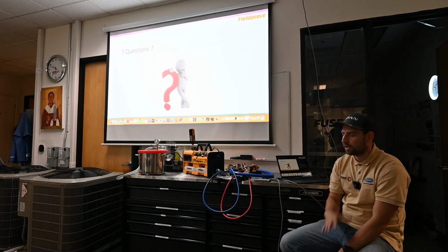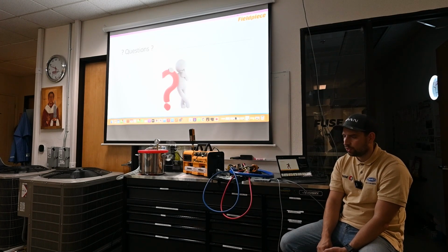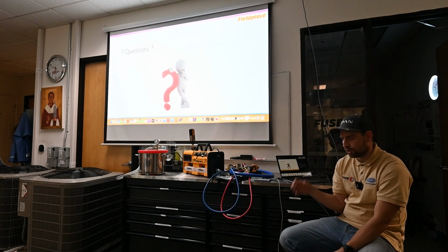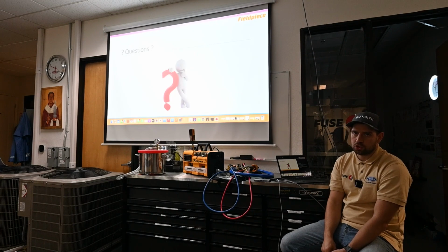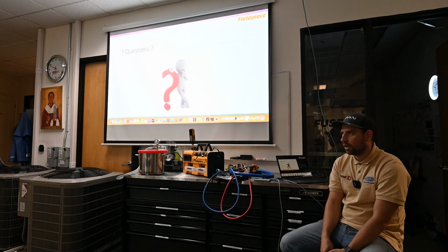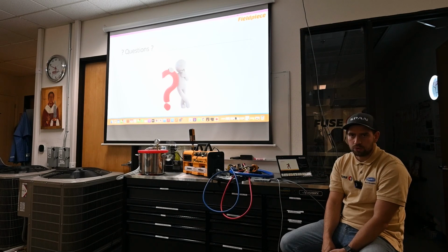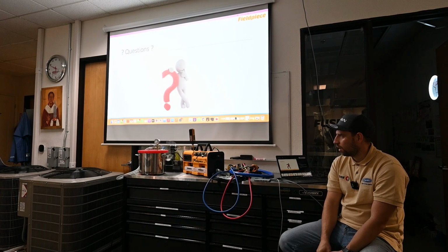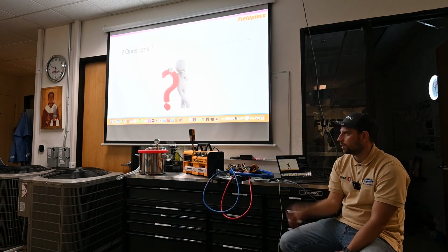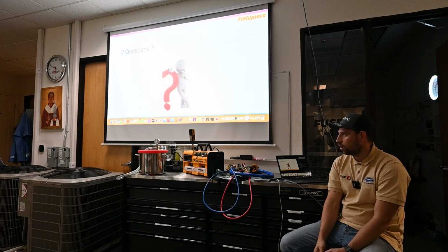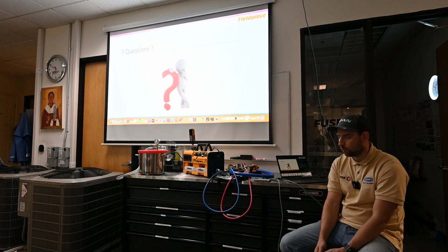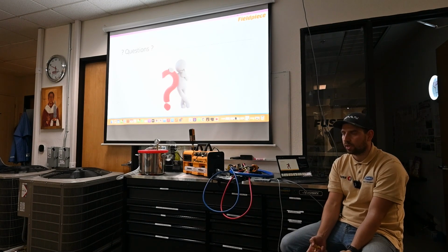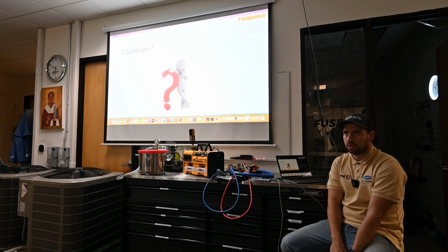If it doesn't help, I will try connecting it to a nitrogen tank and put nitrogen gas in the system. Sometimes I did this job 1, 2, 3 times before starting the vacuum again. This is how vacuum looks like. We are supposed to do vacuum after we install systems, and after we repair some leak of the systems.